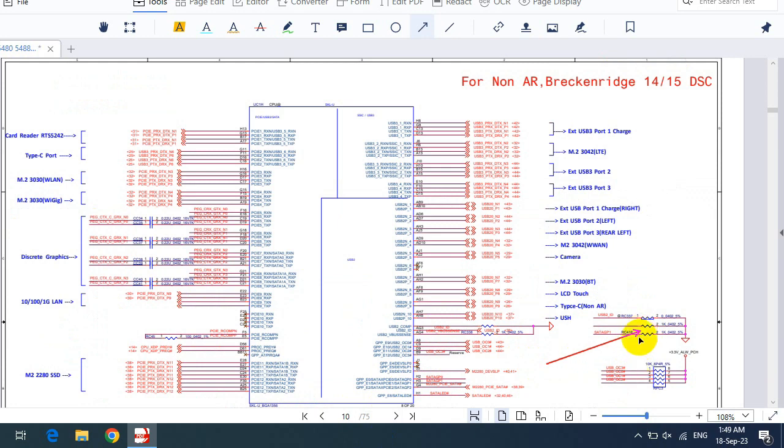So those are resistors, as you can see. Here we have another resistor, but this time it is a network resistor. The definition of a network resistor is a resistor that contains many resistors. It could be 2 resistors, 3, 4 or more. Engineers or designers use this kind of resistor, especially in laptop motherboards and also in computer motherboards, in order to gain space on the motherboard. And of course, the same working principle applies. This resistor here is the same as this.